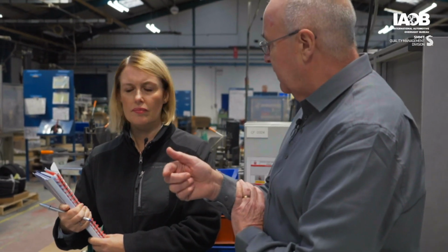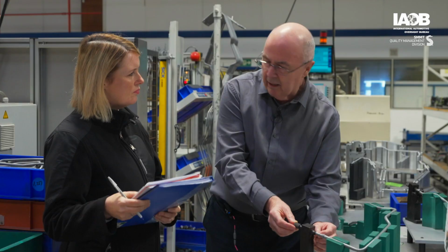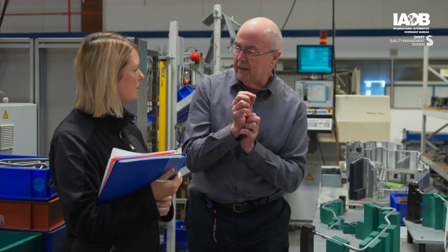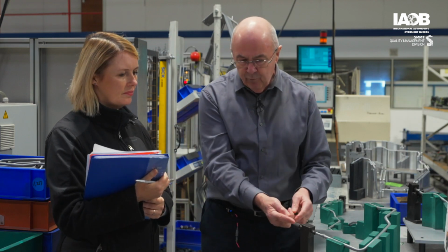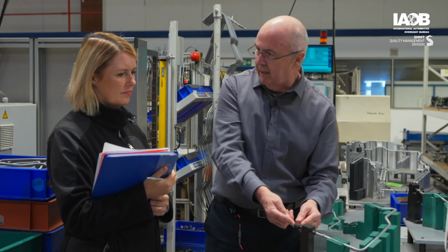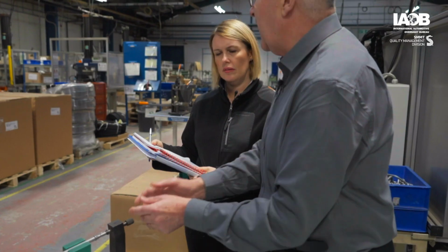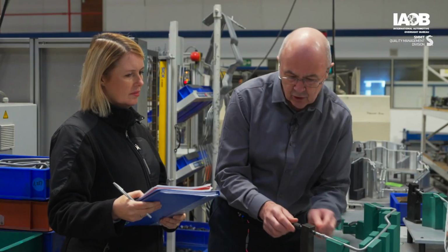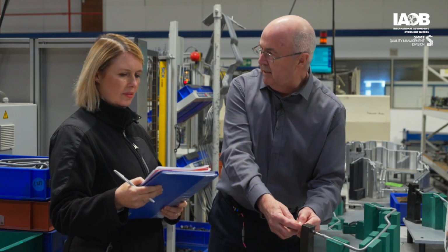Yes. That's because there was an engineering change on this product last week. Okay. So it changed from revision AC to revision AE because this was made longer, because we had a customer concern. So there's been a revision change. Unfortunately, the jig has not been modified yet. Okay, so that's why it shows here as a failure, but actually it's good. I know that's good because I know we're about 1 millimeter from the green zone.